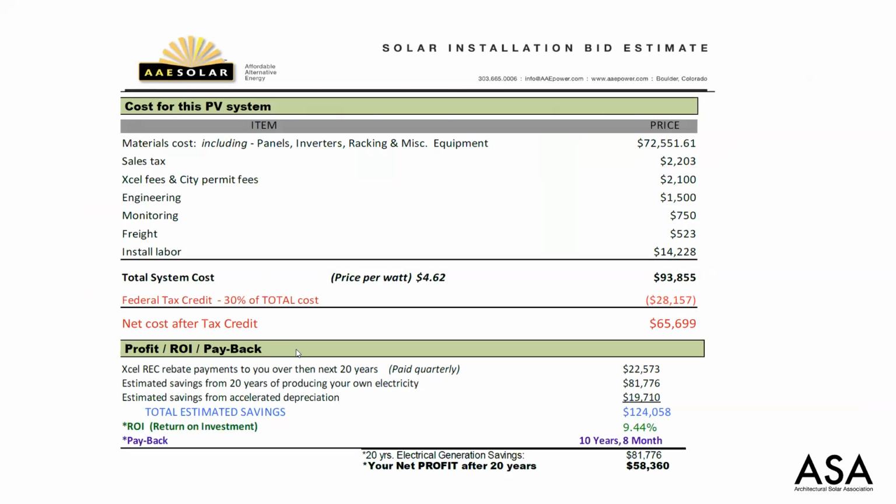Given that there was a clear alternate cladding system, I think it makes sense to model the value that the PV system added to the structure. We can estimate this on a per area basis. So the system area is 1,560.6 square feet, and that translates to about a $60 per square foot cost. After federal tax credit, this comes to $42 a square foot.